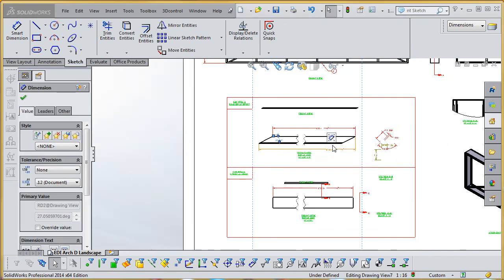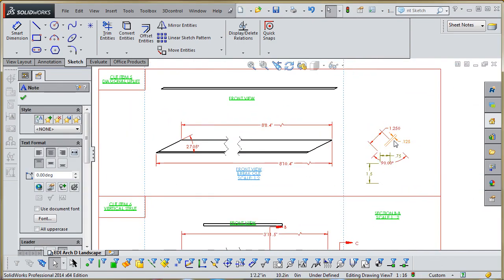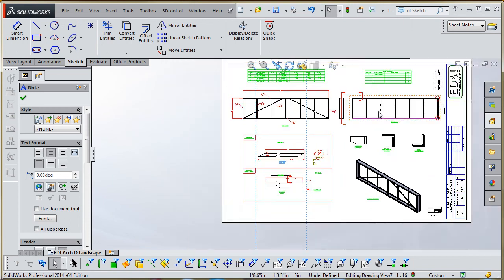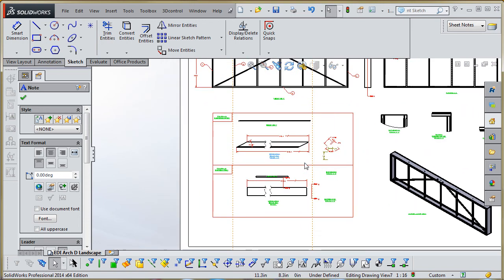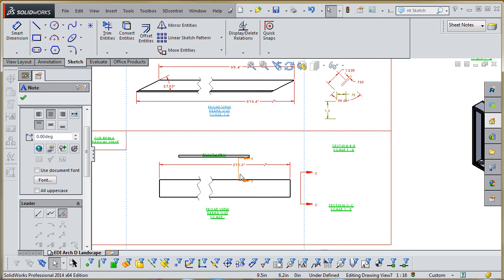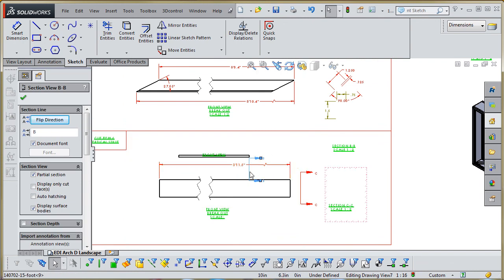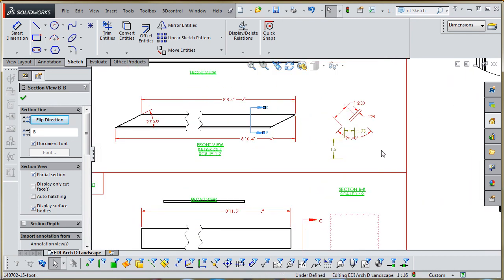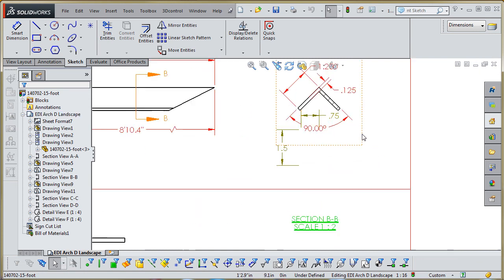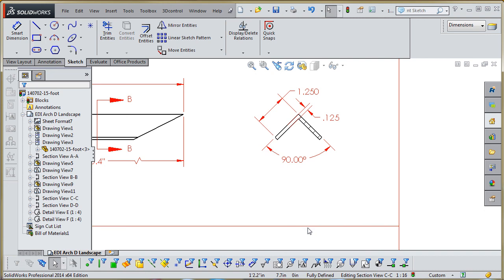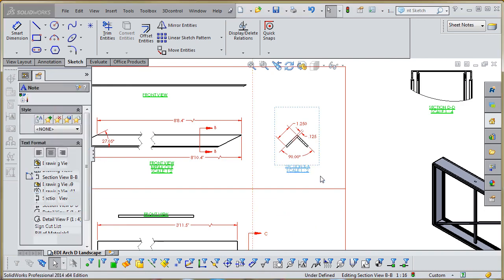Again, you might want to go through your drawing and clean that drawing up a little bit. Our section view kind of got moved off to the side, so we need to find out where those section lines went, which looks like it's down here. So we can move that up here. We can take that section line, move that up here, and then take the end point of that line and move that up here too. Move that off to the side so we can actually grab it a little bit. So that brings that into view over here, and if you rebuild, that brings that section back in. And we can delete these dimensions, which actually refer to the section below. Along with the drawing cleanup, you want to make sure you get your section views in there.